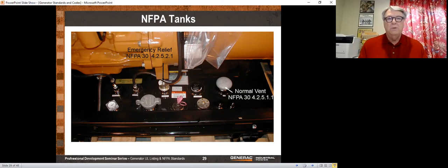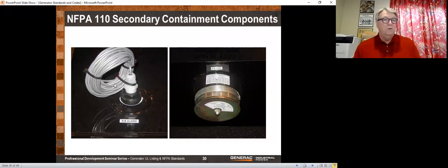And then, of course, with diesel generators, you have two fuel hoses, one that feeds fuel from the tank to the generator, and one that feeds fuel back from the generator to the tank. And modern generators have very little fuel that goes back to the tank. Older generators will have a lot more. That is hot fuel, and that is another requirement you need to consider if you're looking at a day tank. You don't want that day tank to get too hot. This shows a close-up on the left. You've got your fuel gauge, and this is in what we call the rupture basin.